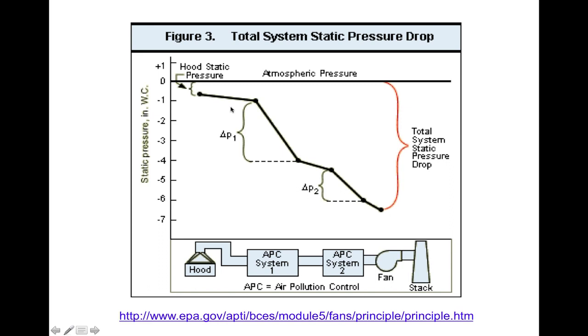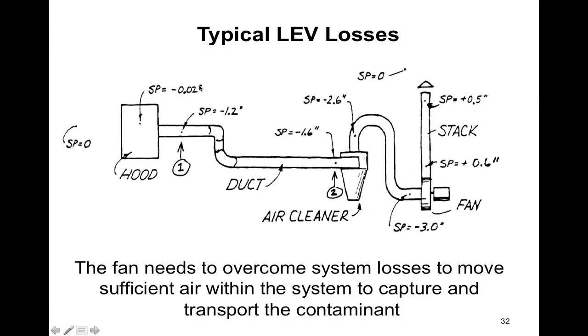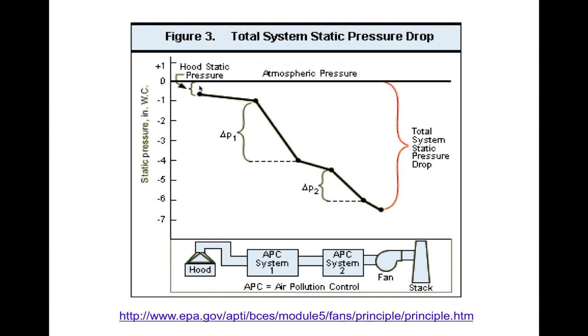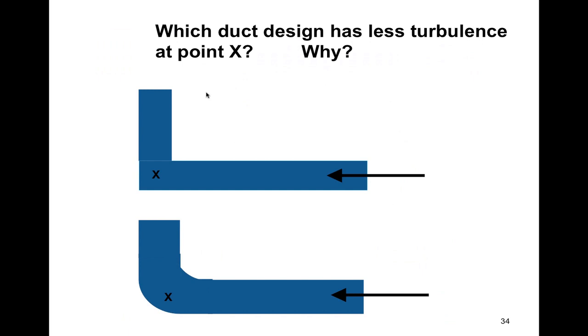And by the time you get to the hood, it's about 1 inch of suction at the hood. So this charts the loss of suction pressure going back from the fan to the hood. They just did graphically what they did with numbers here. That's the only difference. That's not different numbers, but that's the basic difference.